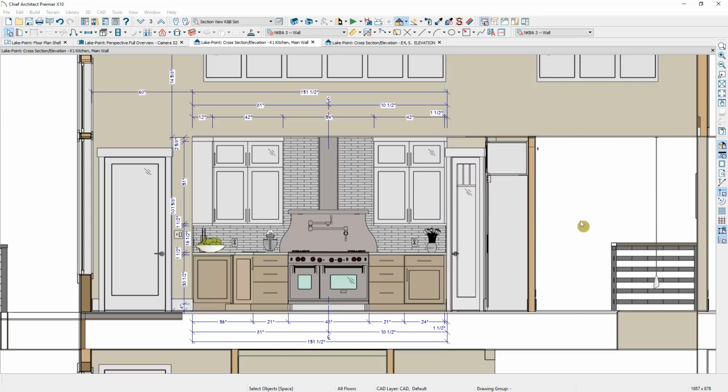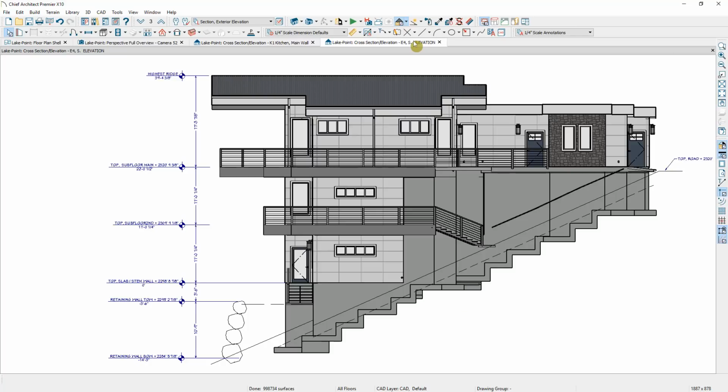When I do a wall elevation, I actually like to use existing dimension defaults because it's very different than doing a section elevation that is typically in feet and goes to different components. So those are defaults that can make your plan development very fast. Again, I'm not going to really touch on that in this video, but watch the annotation set video available in our video system, and also dimension defaults if you want to learn more about that.